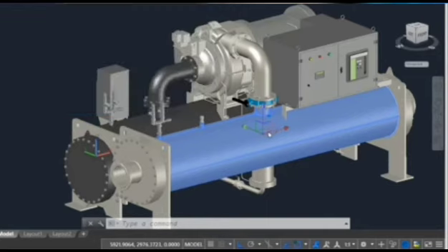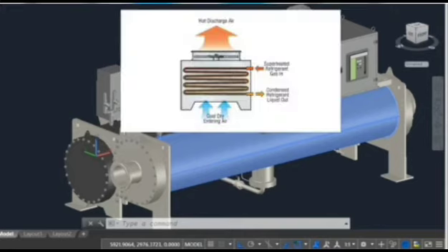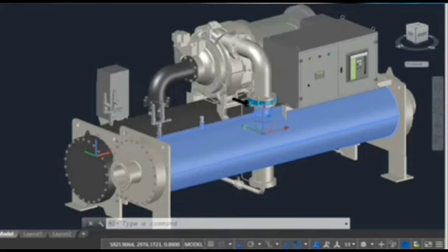However, in the case of air-cooled chillers, there is no cooling tower, but instead air is blown across the exposed condenser pipes to remove heat from the refrigerant flowing inside the condenser tubes. The refrigerant now exits the condenser at point 3 and enters the expansion valve.